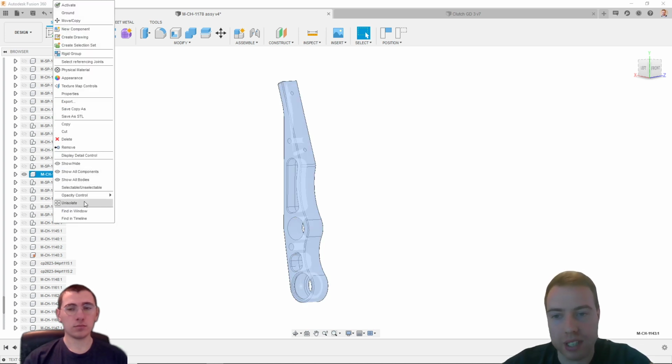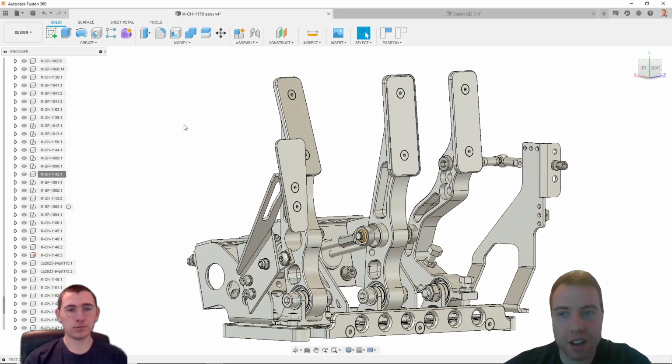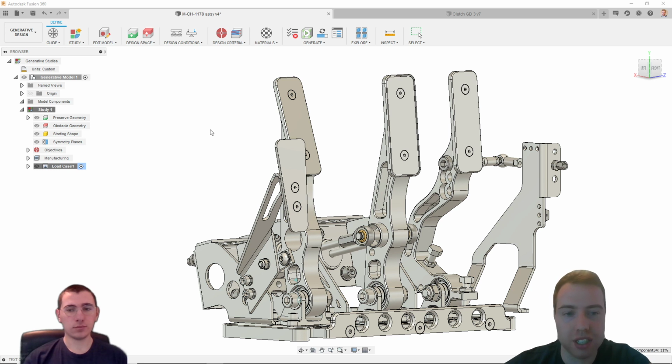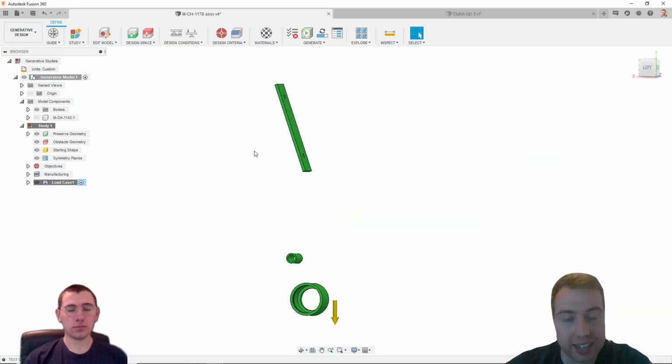That's essentially what we're telling generative design: these three theoretical regions in space are what it needs to perform its core design, and so our final design needs to have this exact geometry in it. But everything else is up to the software to come up with its own solution. And it's going to come up with that solution based on the same reasons why we have that geometry in the existing design. It's going to come up with solutions that are lightweight, high performing, and strong, to connect these three locations.